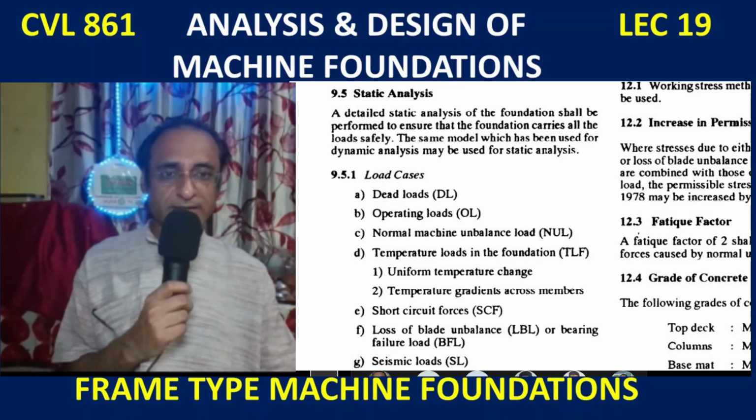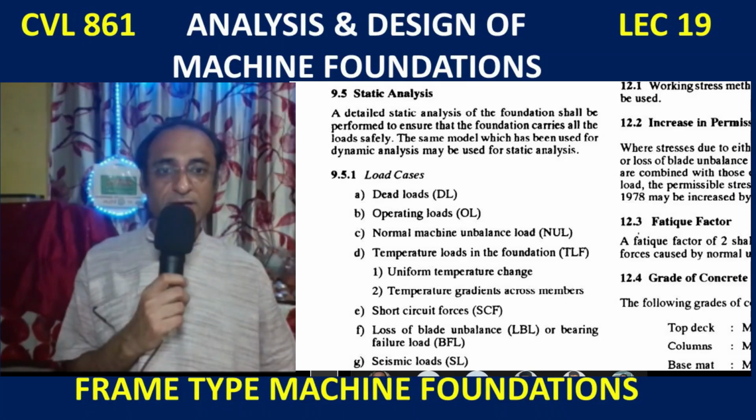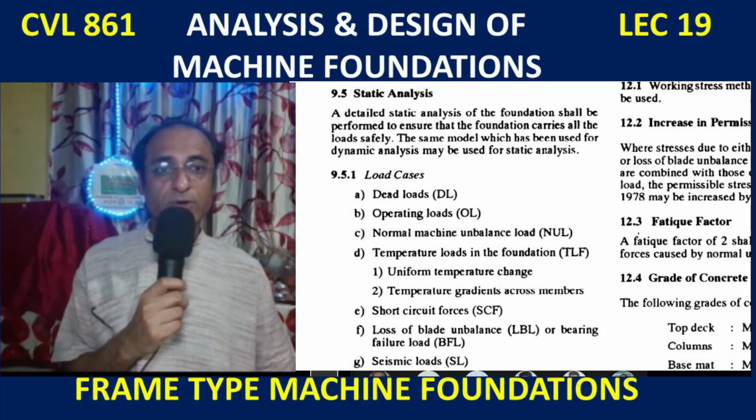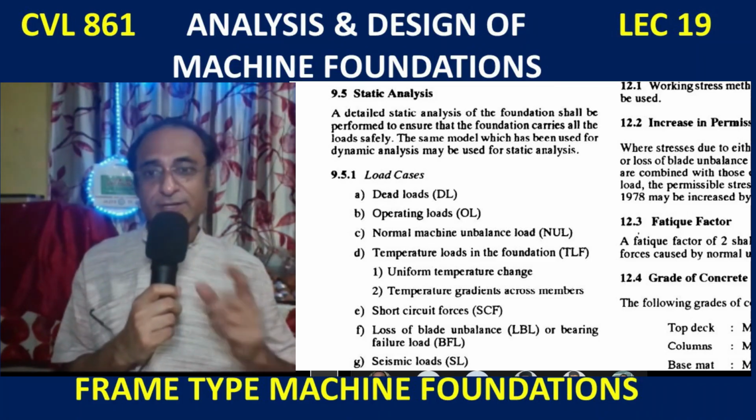I'm just highlighting again. These are the load cases we have to consider, and we have to do static analysis. The code says that a detailed static analysis of the foundations shall be performed to ensure that the foundation carries all the loads safely. So the same model which has been used for dynamic analysis may be used for static analysis. Now it talks about the dynamic analysis.